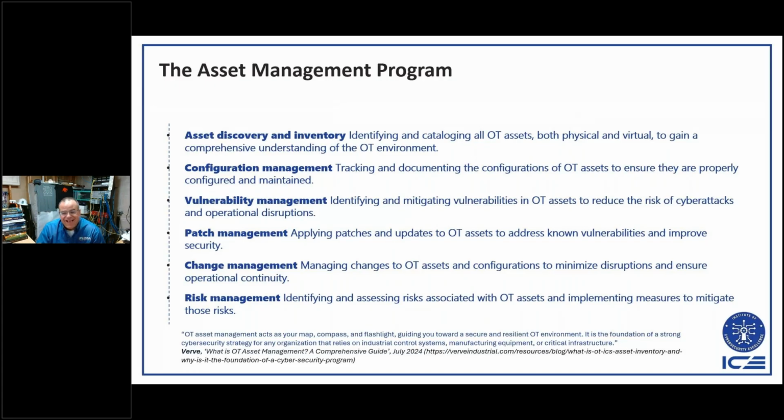There are going to be assets with vulnerabilities that are end of life or out of support, but the value of the asset to the production process or system is greater than the replacement. So part of your vulnerability management is compensating controls and other security to keep a cover, or a shield, if you will, around those aging or legacy assets.